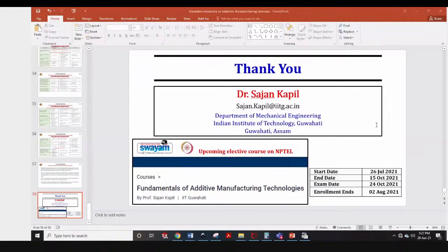Another solution I'll tell you: make it very large, meaning keep the theta lens very close to the laser beam source and then deflect it. But then the throw distance has to be maintained. The laser coming out of the theta lens has to be collimated. If it is not collimated, meaning the diameter is not the same always, then the distance is different and you will not get the diameter you want. So the optics side creates a lot of issues. That is the only reason we are limited.